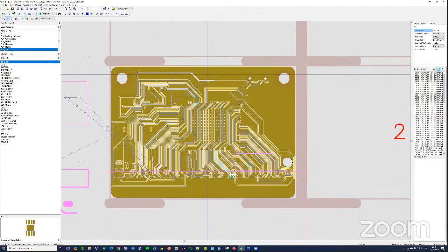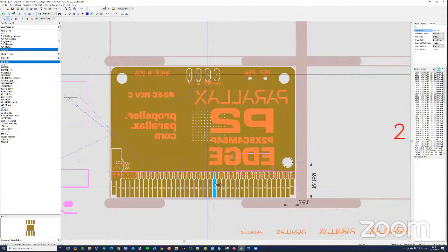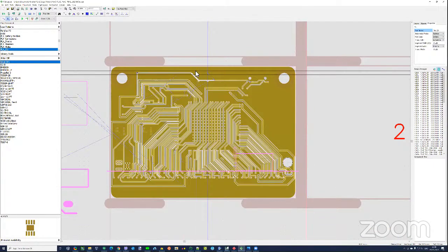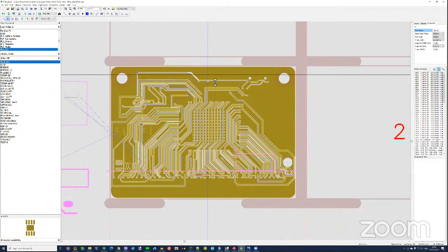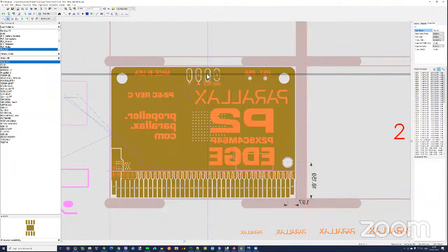But all the signals are all down on there. And then that'll be tightly coupled to the ground plane on the back. And of course, actually, I haven't looked, having added that pad there, if that's going to sit across traces. I need to make sure it's not, but we'll get to that. But yeah, so that's the stack up now.